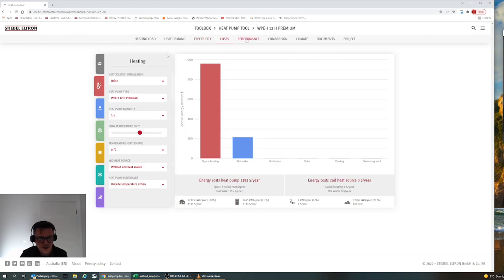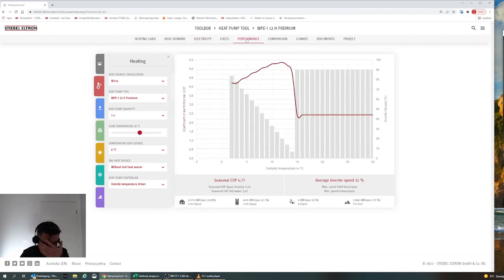Costs, of course, there's a reduction there as well, but I want to know efficiency. That's what's interesting for me. So from the air sourced solution before, we saw that the average COP was 3.9. Now we have a 4.8. So in heating, this solution has a 5.3, and before that we had a 4.1. So that's a lot better. Same here, must be more or less the same percentage in difference, 4.77, 3.9. Yes, it's 22 to 30% savings for geothermal heat pump.